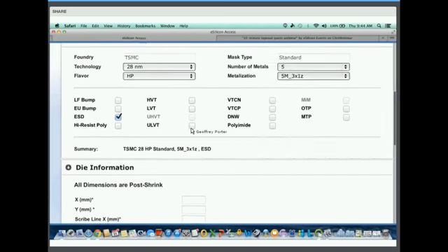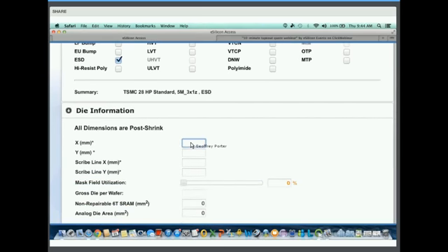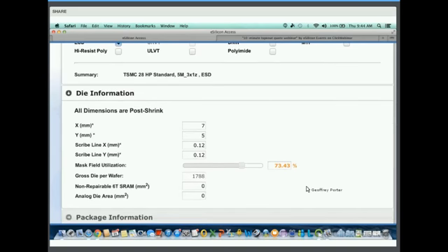So I am in 28 nanometers, which is a process technology node that shows the impact of mask field utilization. If I go here and put in something like 7 by 5, we'll see that the mask field utilization for that die size and aspect ratio is about 73%. Enhanced versions of this tool will not only provide the mask field utilization percentage, but also the optimum die size aspect ratio to maximize that MFU. Yeah, that's a little bit of the guidance that we were talking about. Yes. Great question. Okay.